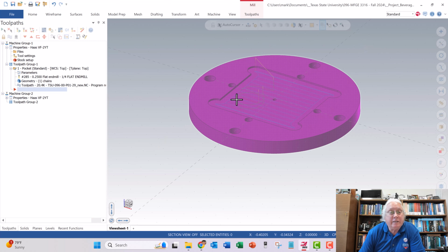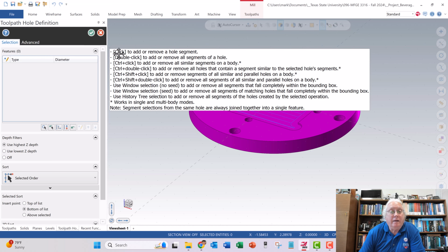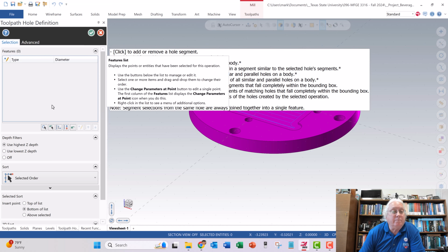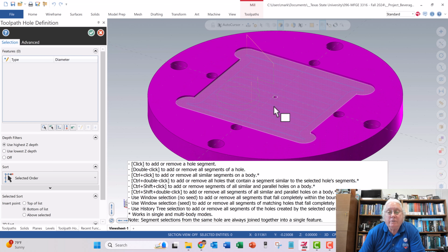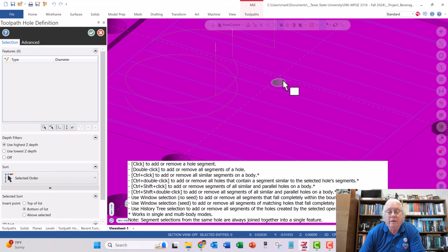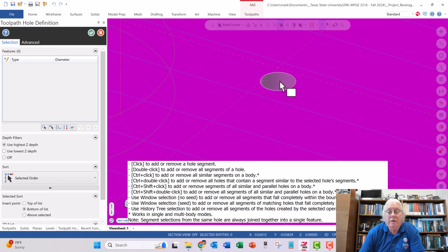Now let's talk about the next feature. I want to drill a hole. I want to drill this 16th inch hole through the middle. So I've got my first tool path, and I want to make another one. I'll go to tool paths, and I'll go to drill. It's going to ask me for some geometry. I want to move this out of the way. I'm going to select this center hole here. I'm going to hover over the circle, and I'm selecting that point right there.